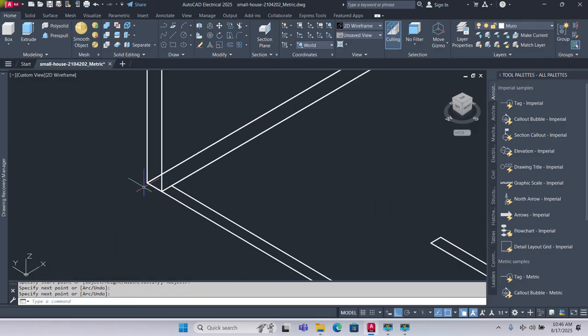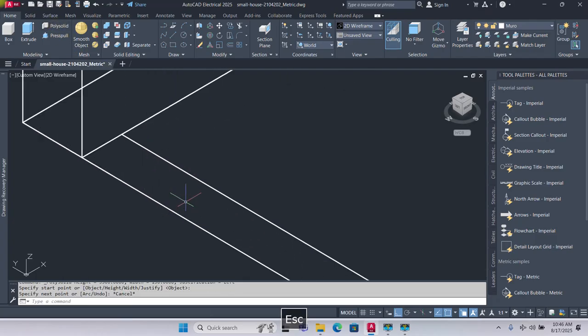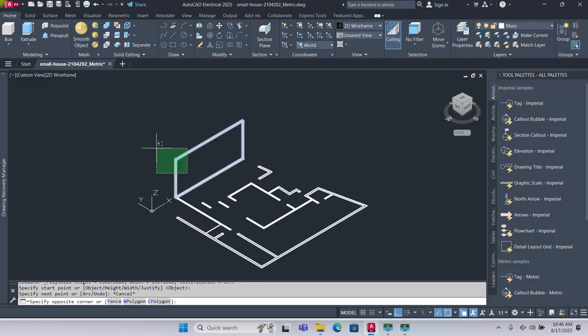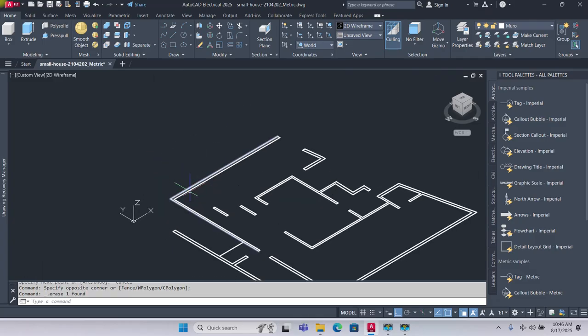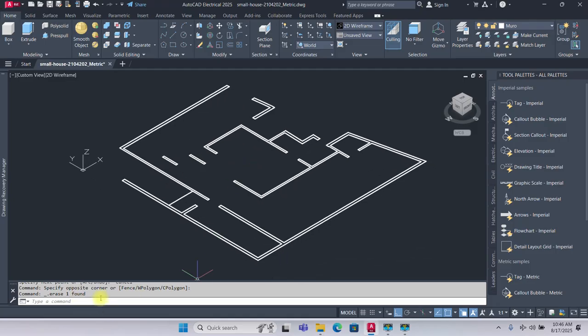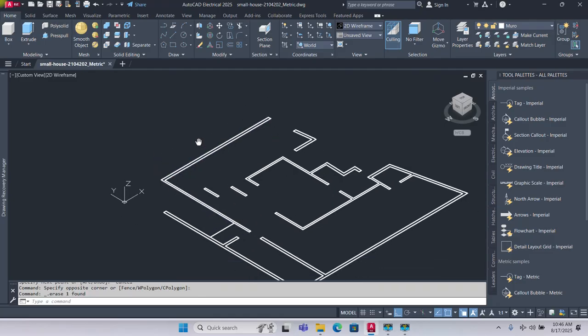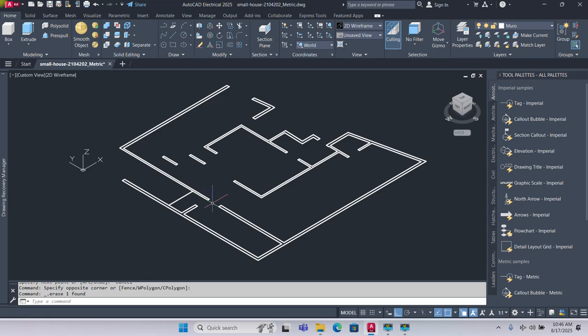If I want to do here again and I do that wall, let's say this point, you will notice that it is wider. That means I have to come back here, check the dimension, and set again, and it's going to be tedious. All right. So instead of using that approach, you can just use what we call the region command. That region command will look at all this and make them a solid region. Then we can just extrude them.